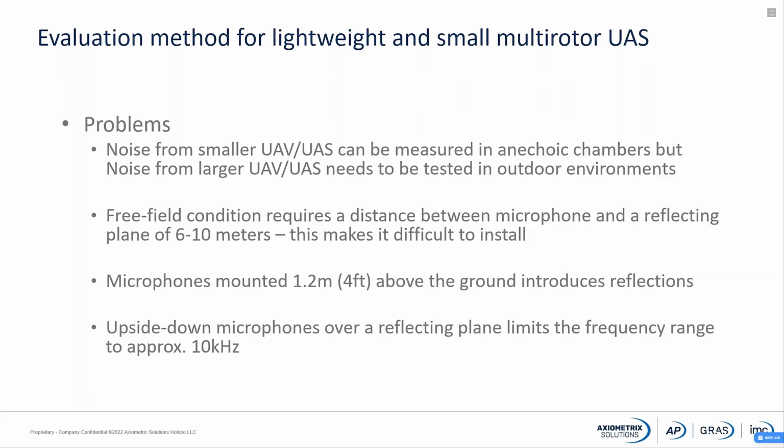If we use the 1.2 meter or 4 feet above the ground, that will introduce reflections, and that is not really good if you have a stationary source or tonal content. Then we can also use the upside down microphone, but that is not going to work for frequencies over 10 kilohertz. So regardless of what we already have in the standards, it's not really useful for doing accurate measurements on UAS.